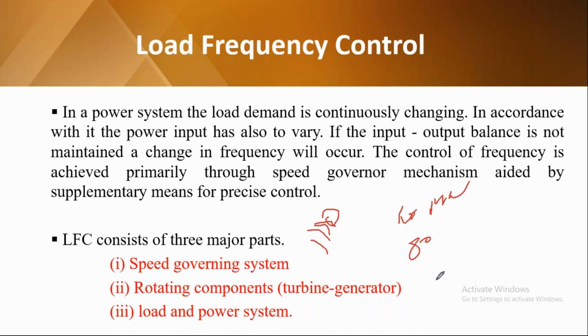Suppose the turbine should be rotating more, so why? Because the generator has more demand load. What do we have to do? The speed of the turbine has to be more, and this can be achieved by increasing the inflow of steam from the steam valve.